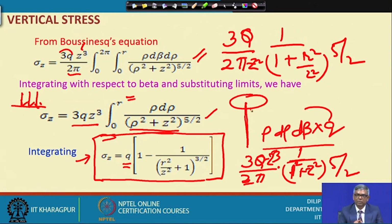So right now, whatever we have got is at any vertical depth through the center of the footing, and that is critical. That means when a circular footing is loaded, the stress below the center of the footing is supposed to be more, and we have got the expression for that. Okay, so this is the one for the circular area to be integrated.